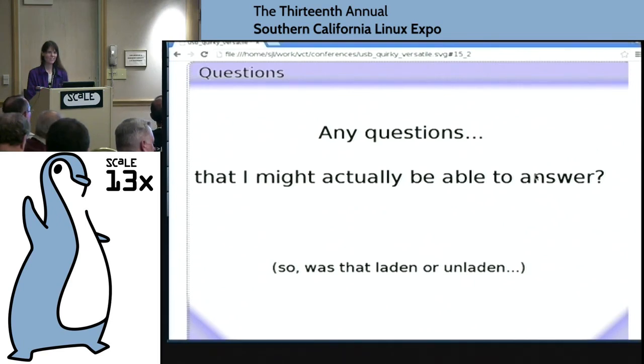This is a fairly general question about how USB works. A few years ago, I noticed that there were changes in the implementation on how to verify the integrity of data when it gets transferred across USB. In fact, I remember one Windows system I was looking at was actually implementing TCP/IP over the USB connection. It's maybe a little off topic from what you're talking about, but how does USB verify the data integrity as it's being transferred? There are checksums, but they're optional, and not all protocols use it as part of the low-level USB. So I think it depends on the protocol.